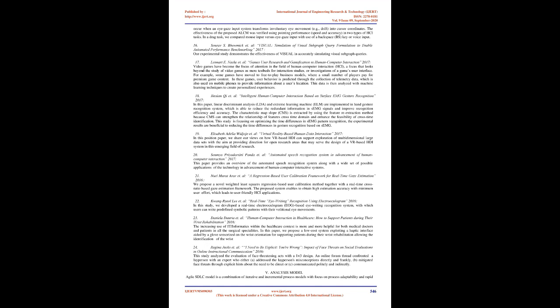This paper proposes a hand gesture recognition system for a real-time application of HCI using 60 GHz frequency modulated continuous wave, FMCW, radar, solely developed by Google. The overall system includes a signal processing part that generates range Doppler map, RDM, sequences without clutter and a machine learning part including a long short-term memory, LSTM, encoder to learn the temporal characteristics of the RDM sequences.